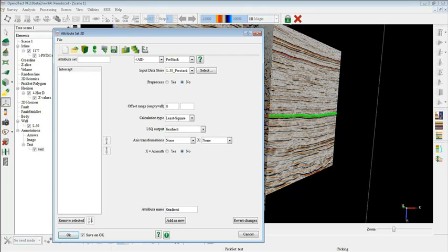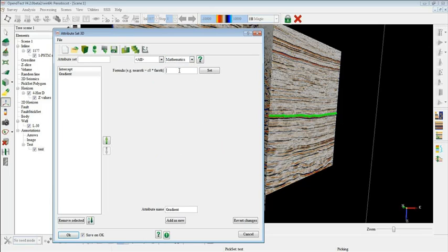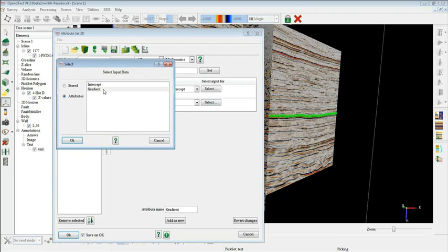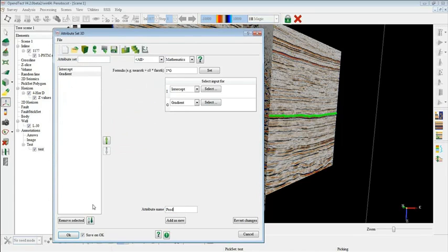Currently this is the simplest, least-squares output available for pre-stack data in OpendTect, and you can use mathematics together with this to create more attributes like product. For the I variable I provide intercept as an input, and for G I provide gradient as an input. Call it product, sum and fluid factor. I can write those equations simply in here. The purpose was just to show how you're going to use two or three attributes, using one attribute as an input of the previous one. And you can do cross plotting, and you can calculate these attributes on the fly on a section, and that's it.